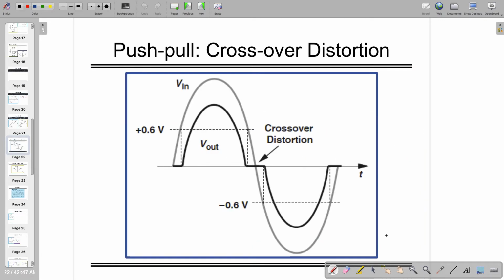So drawing the characteristic when this is VBE1 and this is VBE2, you're going to experience the output, but still crossover distortion will remain there. So the amount of crossover distortion might be small, but still it's there because of the dead zone. This is coming because of the dead zone. So let's keep this in our mind that this is a problem from the push-pull stage.